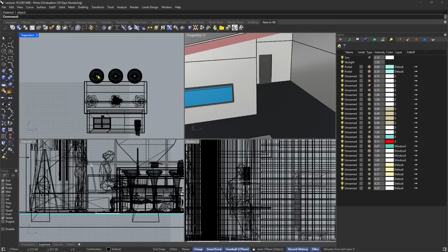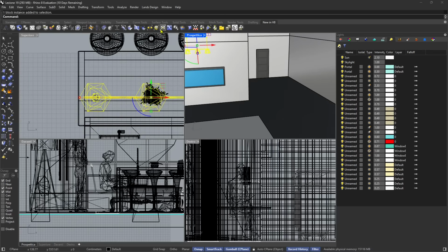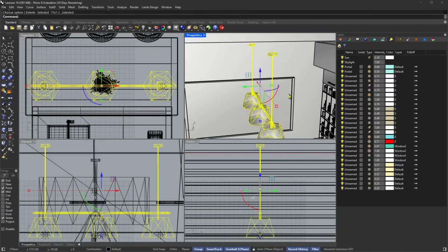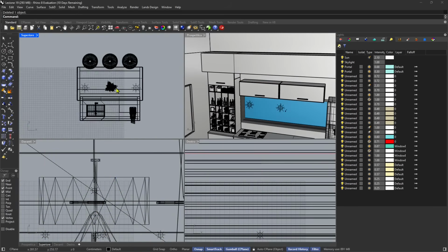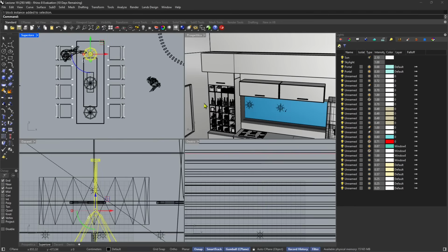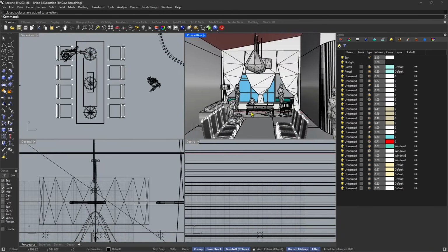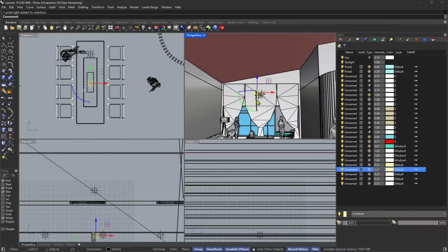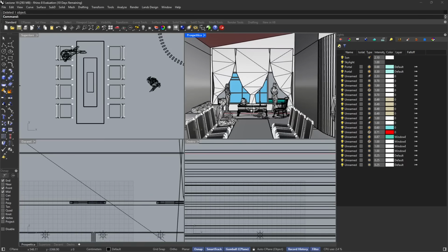So I have some models here from Enscape, which will be visible just as proxies. Let me zoom selected. Zoom selected is a wonderful tool to get your camera right into the point where you want to work. So you can see, delete all these proxies because they come from Enscape, and they will not be good when you render them in Rhino unless you're using Enscape. And you can see, if you want to put a lighting device, artificial lights, remember you need to put a light on every device that you insert. There I have a lamp, and inside I have an Omni light.